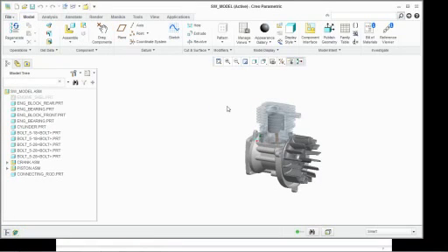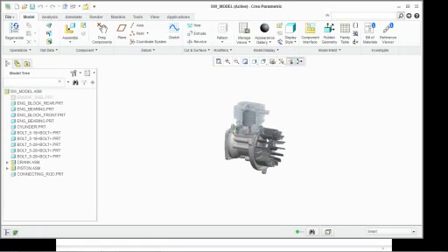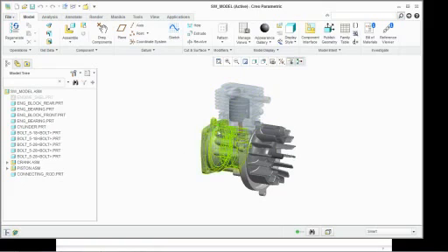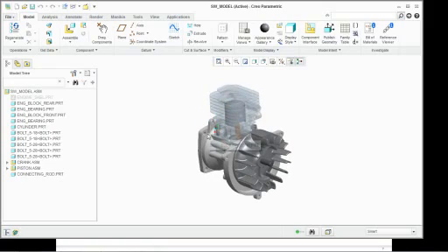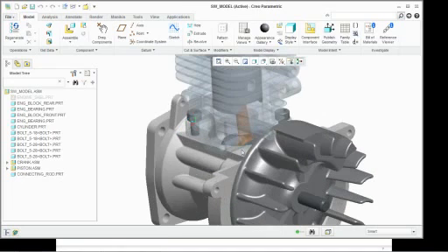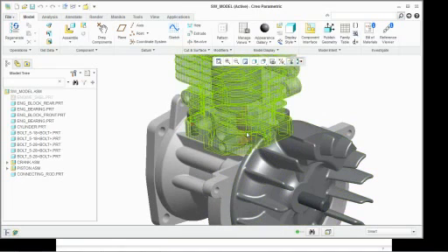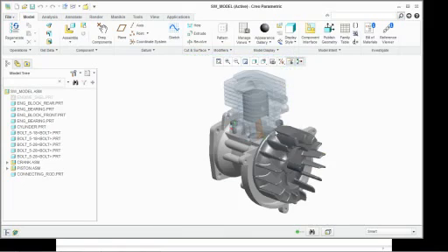So now we're going to come in, and the point of a shrink wrap is to take a large, complicated assembly with lots of components inside of it, and to actually create another part you can substitute into that assembly, maybe using an envelope, to simplify how this fits into an assembly. If this is a really large assembly, I don't need to know all of the details of the piston and the crankshaft and the connecting rod inside. I just want to see maybe the overall geometry, the overall surfaces.